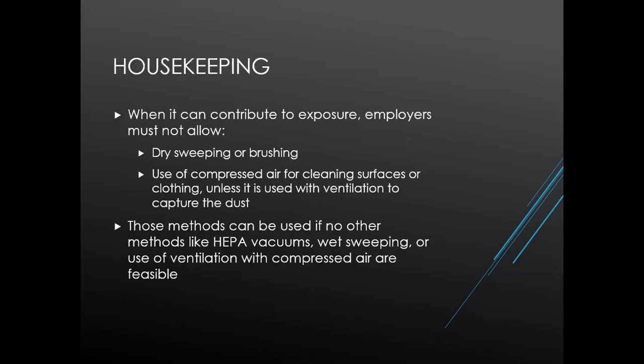For the purposes of housekeeping, we want to ensure that we are not contributing to an employee's exposure during this task. And for this reason, the employer must not allow dry sweeping or dry brushing, as these can increase the amount of dust in the air. And the same can be said for using compressed air to clean clothing or surfaces. Instead, we want to use wet sweeping or mopping, or use a HEPA vacuum for cleaning, but only if they are feasible. If they're not feasible, then the other methods of housekeeping can be used.